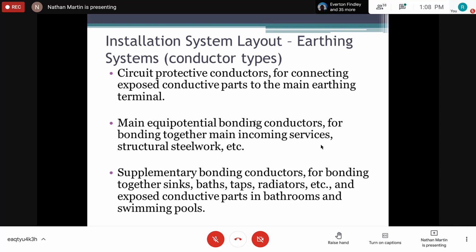So what that is saying is that your earth conductor can be one size less than your phase conductors, right? But just to be safe when we are doing our installation, we normally select the earth conductor to be of similar size as the phase conductor. And that is when we are using single core cables, all right? That's when we're using single phase cables.